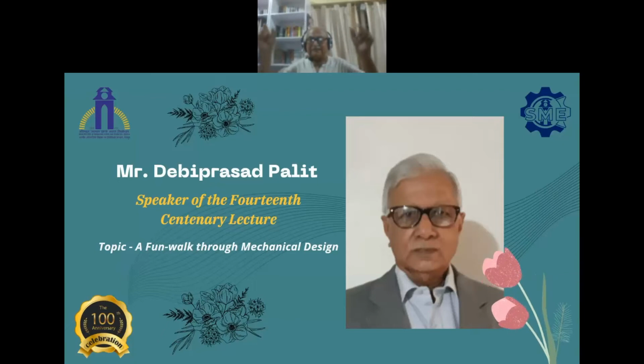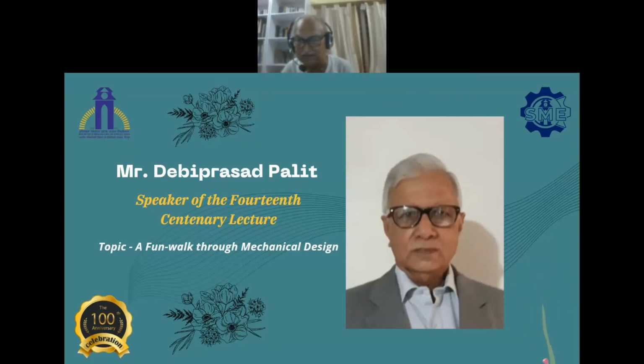Now, another 2-3 minutes. The factory was made in the form of a 2-hinged portal. The bottom of the base is hinged, then the concrete members, and then the steel top. What the crane manufacturer did, it's a 10-ton crane or something, in their happiness they put two 10-kilowatt motors on the two sides for the long travel. But the two 10-kilowatt motors were more than sufficient to give acceleration, and it was slipping. So much rotary acceleration was being provided by 20 kilowatts in the long travel, where maybe 5 kilowatts is needed, that it was accelerating much more than the inertia of the machine could permit it to move.